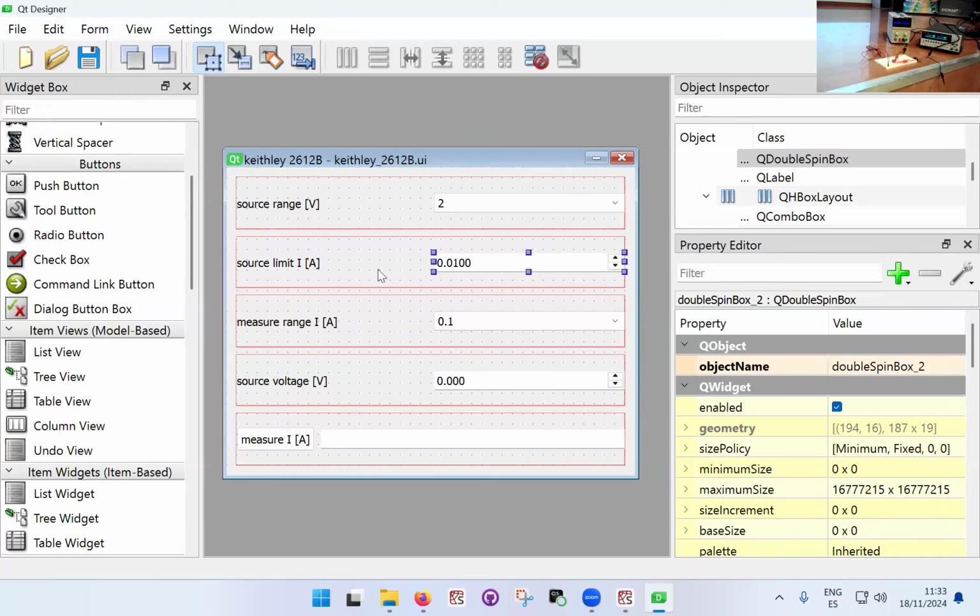Well, this is actually something you can, specifically in the Keithley, set independently. The way it works is that you tell it what voltage to output, and you can tell it to have a current limit. So generally what happens is you apply a voltage to whatever circuit you've got. But the maximum limit of the intensity that you can get is related to the maximum power that it can store. Yes, of course. So that limit will be different if you have the range of the voltage. Yes, definitely. The Keithley will allow you to do that, it will just give you an error. So I can set the range to be lower if I want, because I can do it manually.